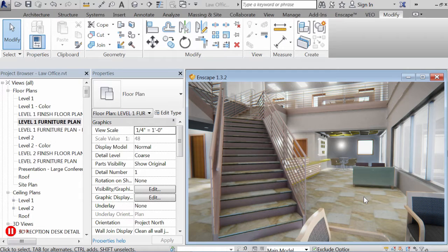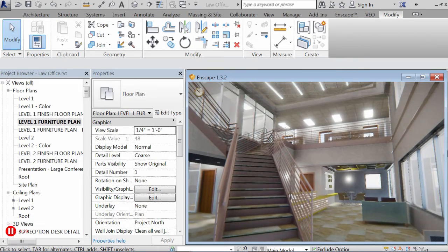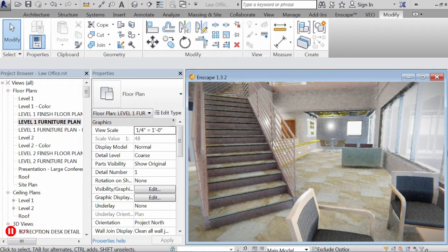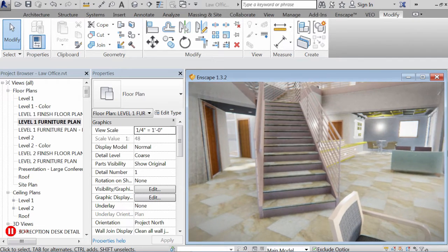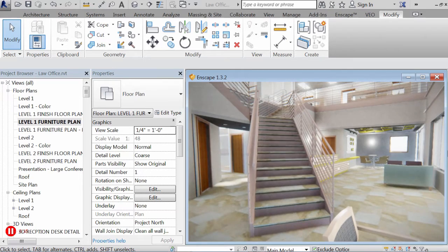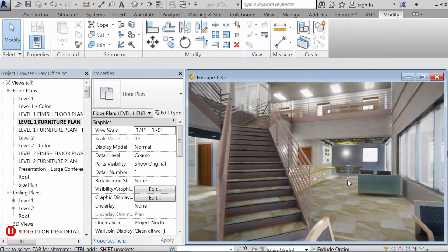Right. Well, there's several things that we can see right in this view. There's a pretty intense coverage of materials and the material editor. So you can see the floor tile that's showing up here and the need to get the correct texture, the correct size and orientation. There's also coverage of Revit's synthetic materials, as I like to call them. That's a little known feature in Revit where you can make your own materials that have different colored grout joints and staggered patterns.